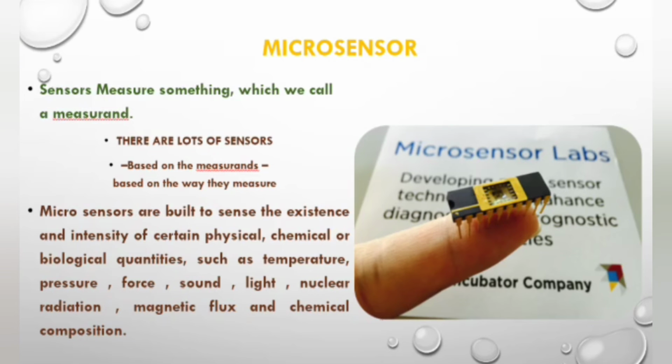Variable capacitive MEMS accelerometers are lower range, high sensitivity devices used for structural monitoring and constant acceleration measurements. And piezoresistive MEMS accelerometers are higher range, low sensitivity devices used in shock and blast applications.